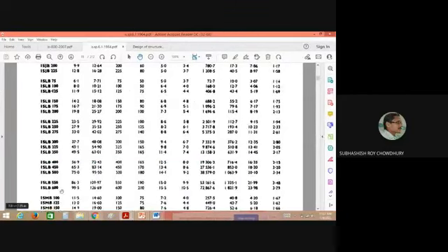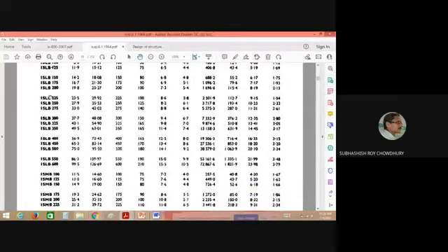Now if you go to the ISMB 150, you will see that ISLB 150 is having 86.8, 4.8. MB is 80, the same, but it is 7.6, 4.8. So ISLB and ISMB have the same width of the flange. This is the width of the flange for ISLB 150, and for ISMB 150, this is the width.